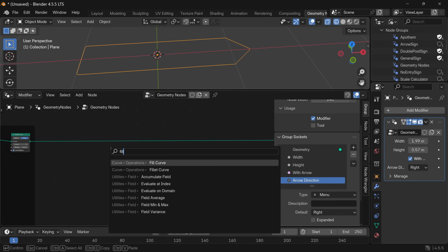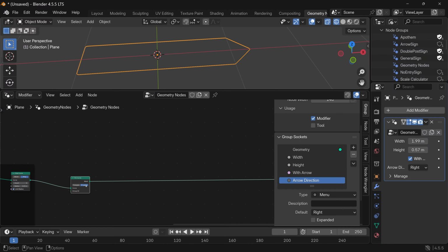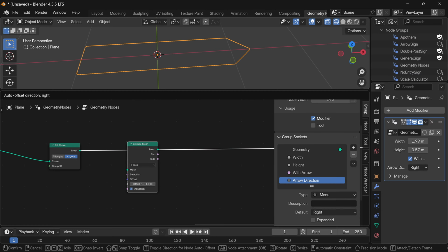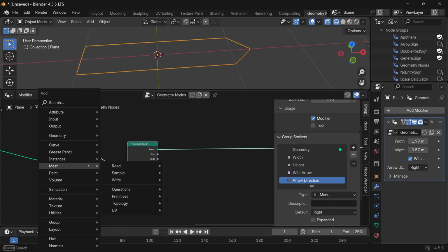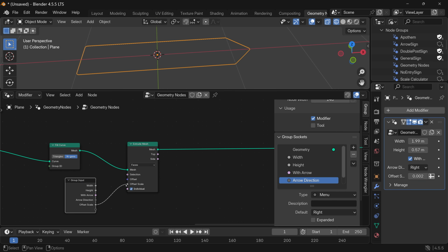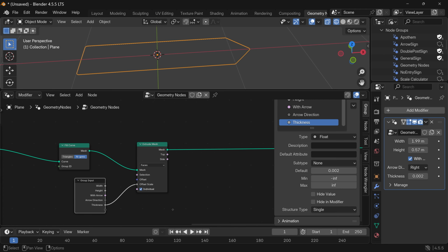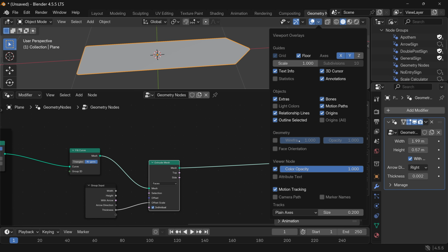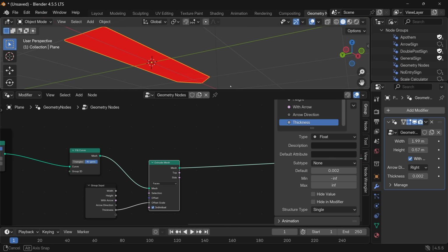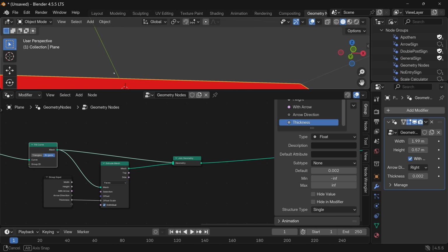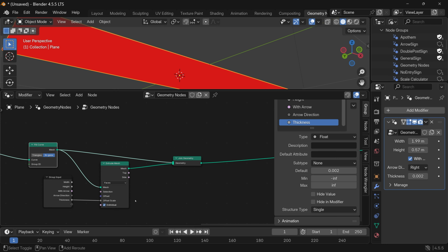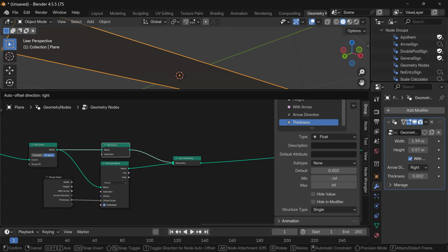I'm gonna fill this curve and extrude the mesh. And this is our thickness value. Alright, let me activate face orientation so we can check it. Now let's join this extruded mesh with our previous face, and we can see the face is not properly oriented. So let's flip this face and we are good to go.